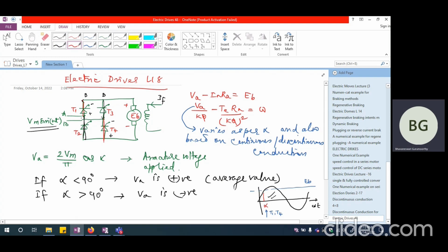So whatever logic we applied for turning on T1 and T4, the same logic we should be able to apply for turning off T3 and T2. So now T1 has started conducting, so that becomes a short circuit. T4 starts conducting, that becomes a short circuit. So this point B now comes into existence here also. This is going to be B, and this point is A anyway. So VAB is positive, which means that is going to reverse bias T2.